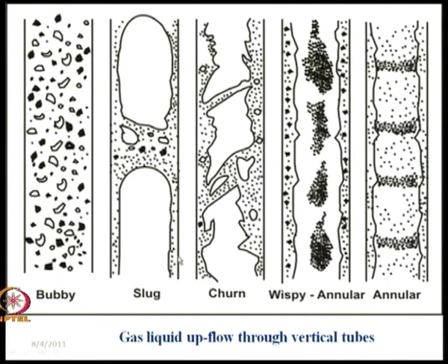Then it comes down and finally meets the liquid slug beneath. When it meets, naturally a good amount of vorticity is produced. Due to this vorticity, some amount of air is sheared away from the surface of the bubble and tends to aerate the liquid slug beneath. Usually the aeration is more just below the bubble as compared to further downwards.